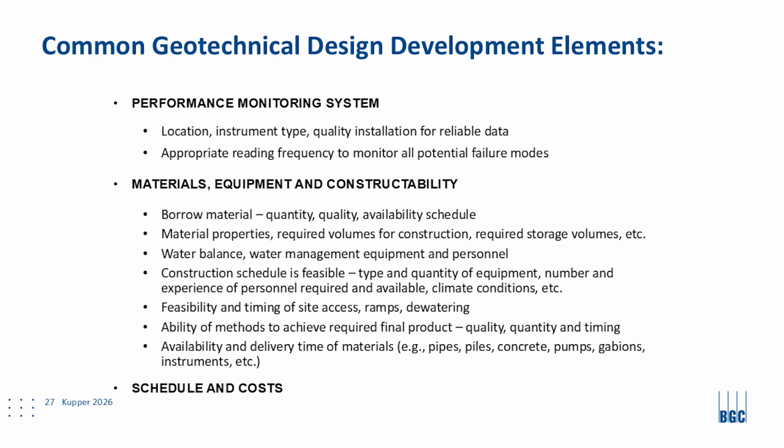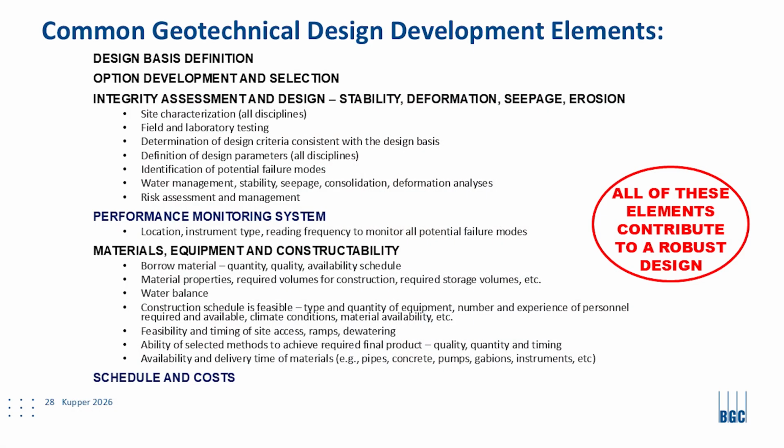If you need your basal drain, obviously, to be built at the base of a dam, but that part of the borrow area that's got good sand is only available at the end of construction, that's not going to help us. So obviously construction schedule and availability of material is really important. But another thing about construction schedule, if you assumed pore pressure dissipation, is it going to be dissipated by the time you finish construction, or are you going to have to make different allowances in your design? So all of those things are very, very important. But the bottom line is the entire list are elements that contribute to a robust design.